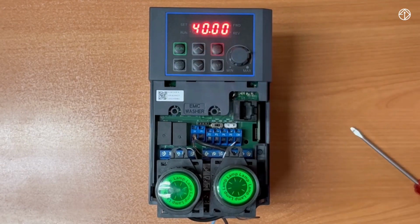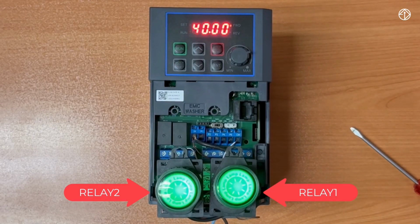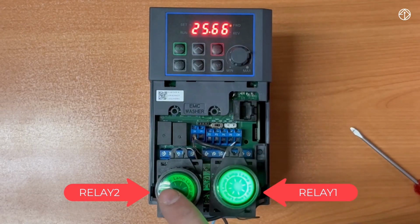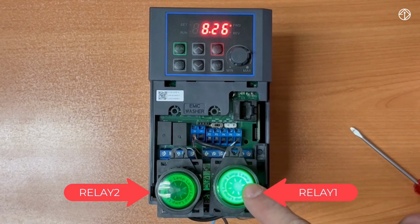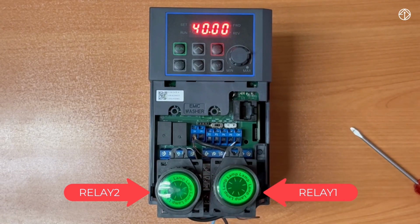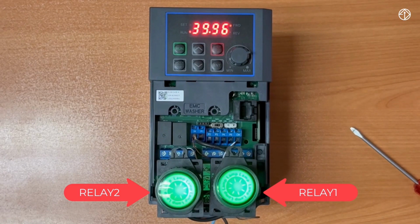Relay 1 should activate as soon as I run the inverter. I start it, and you can see that relay 1 activates. When it reaches 40 Hz, relay 2 also activates. Now I stop the inverter. You can see that relay 2 deactivates first, and since the inverter is no longer running, relay 1 also deactivates. I'll start it one more time. I start it, relay 1 activates, and when it reaches 40 Hz, relay 2 also activates.